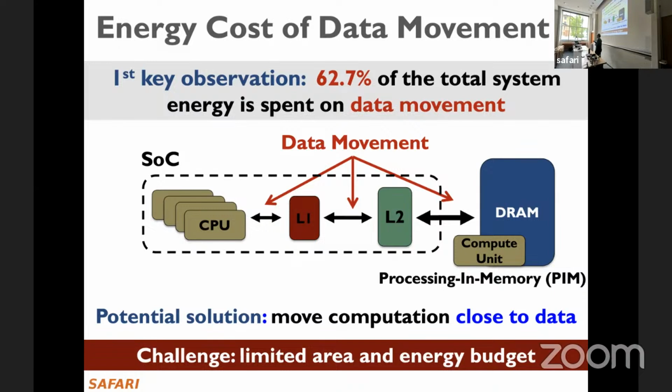And the paper has some analysis. One of the issues with putting computation in a logic layer underneath memory layers is thermal issues, right? Because if you put computation and memory on top of each other, now you have heat that has nowhere to escape. In current processors, it's two-dimensional. You don't have 3 dimensions. Well, in some existing ones, you have 3 dimensions. But if you have a two-dimensional processor, the heat can escape from the top, and you can actually remove the heat using a heat sink, right?